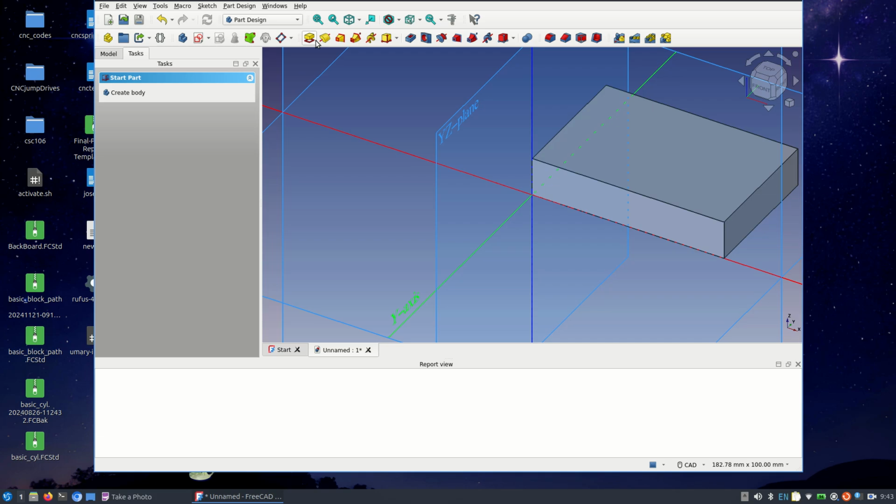Depending on my step down, which is after every pass that I cut, I go down. After I pass it again, I go down. So that's the step down. If my step down is actually, let's say, 15 millimeters, then it's going to go 15 by 15, right? But if my step down is actually 3, and I already cut the thing all the way through, I can just stop, you know? So I have to watch for that.